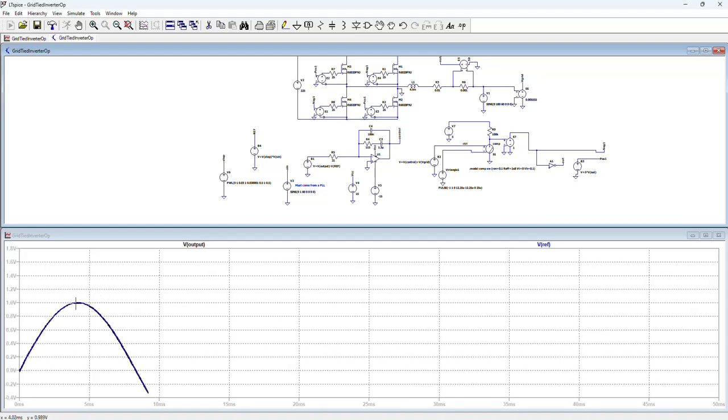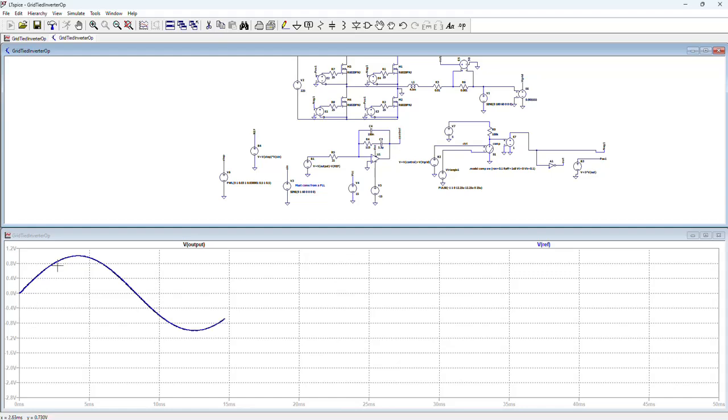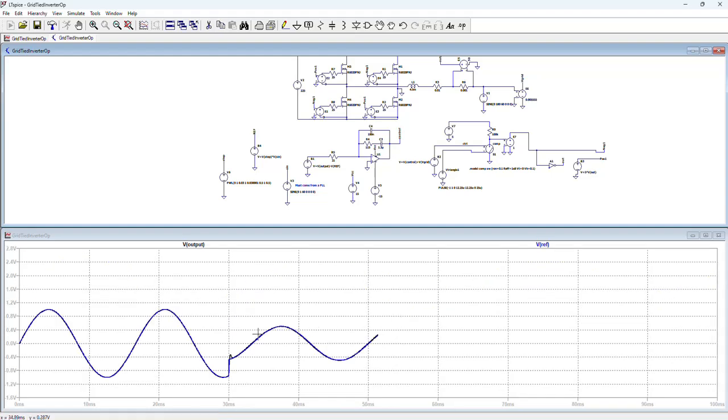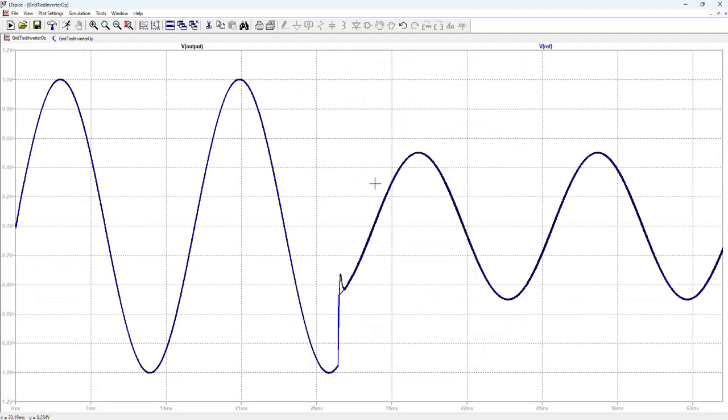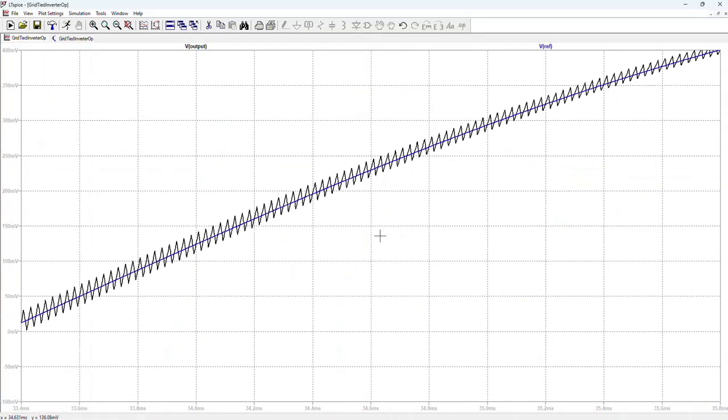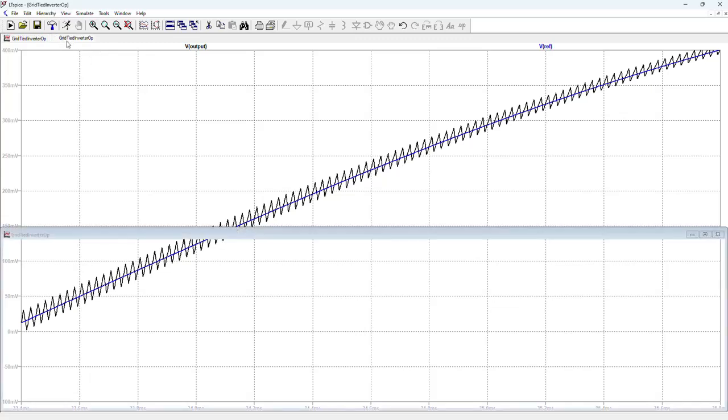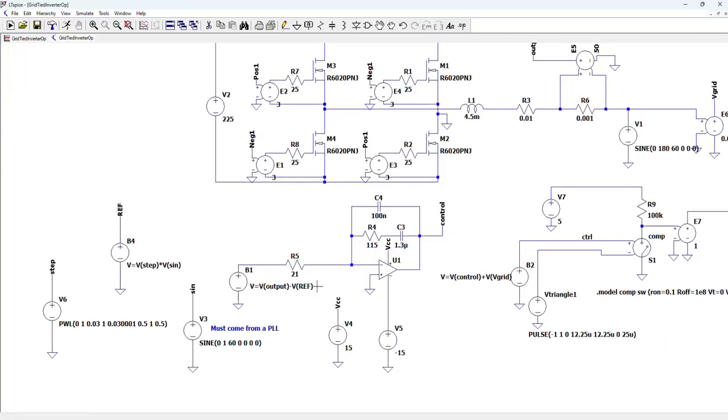My current initially varies from -1 to 1, which means -20 to 20. In 30 milliseconds the step will happen. We can see here how the controller behaves in the system. It seems that the controller is working well, even for the reference from 20 to 10. This is good, this is enough. It also shows us that the controller is properly designed. I can apply a zoom here just to check how the output current is following the reference, which is good. This is the first step I'd like to test.